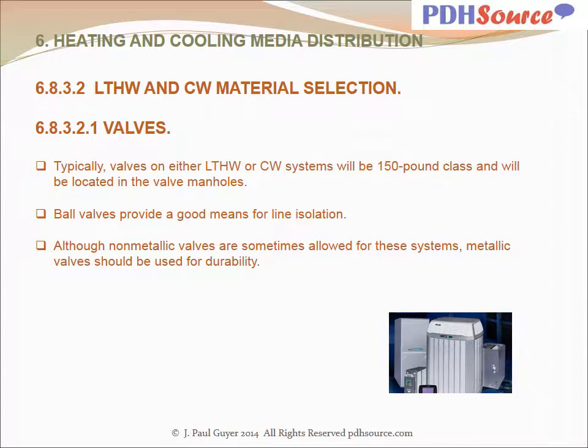With regard to material selection for low temperature hot water and chilled water for valves, typically valves on either low temperature hot water or chilled water systems will be 150-pound class and will be located in the valve manholes. Ball valves provide a good means for line isolation. Although non-metallic valves are sometimes allowed for these systems, metallic valves should be used for durability.